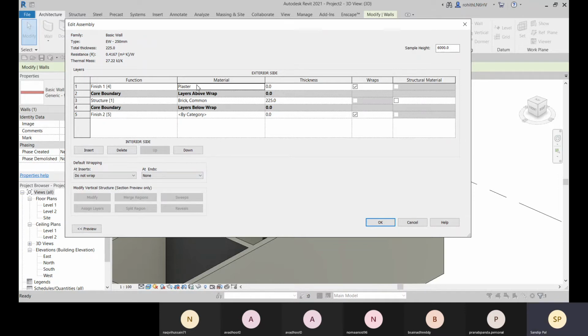So that is plaster. And here you can just simply Ctrl+C, and here you can simply Ctrl+V, paste it. That is applied. And about the thickness. So thickness is 12 mm, and here you can go for like 13 mm, just because this is the exterior side. Or else both sides you can go with 12.5 and 12.5. Okay, so this is created.